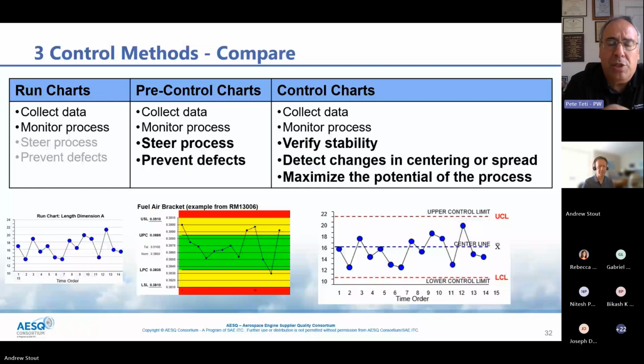it's in a practical situation, where I think of the example in the reference manual where we add the viscosity level in a casting process. And we have a warning line that says if we get near that line, we need to add water. And that's a very practical thing to do. Control limits in that case may not be applicable, but that warning limit is very applicable to the casting process. So run charts with warning limits could be very useful.